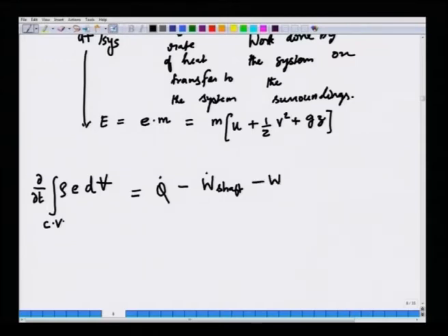Then we also had, in general, a shear work done at the entry and exit through the control surfaces, but we also said that that can be normally set to 0 by choosing the control surface perpendicular to the flow velocities. Okay. But this is not all.